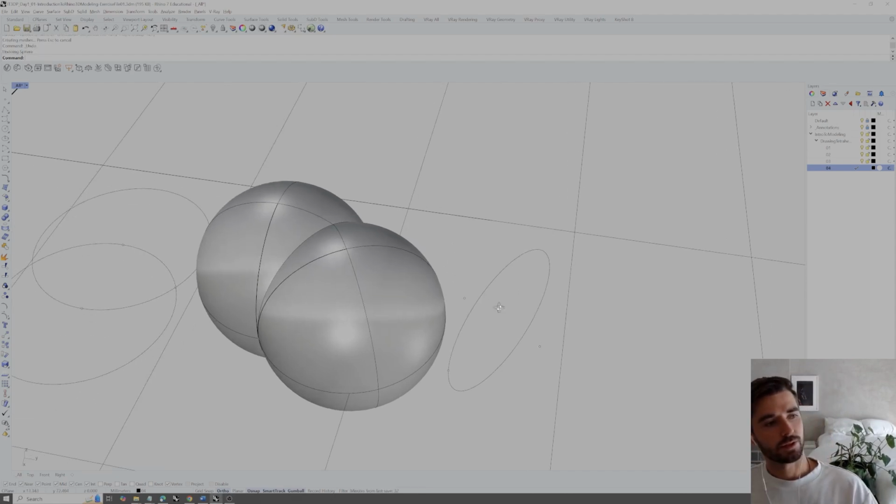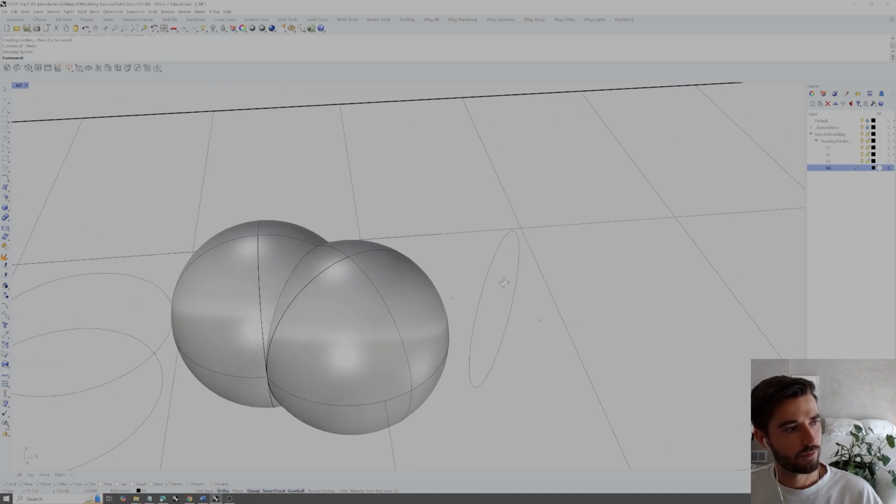So 10 units from each one of these points. What we need is a sphere drawn here from this base point, or this kind of middle point, point 2, which has this vertical circle drawn out, but a sphere drawn from this point now to one of the other points. That is going to ensure that the radius is of unit 10. We know this because the centroid is at point 2. The distance from point 2 to, let's say, point 3 is 10 units.